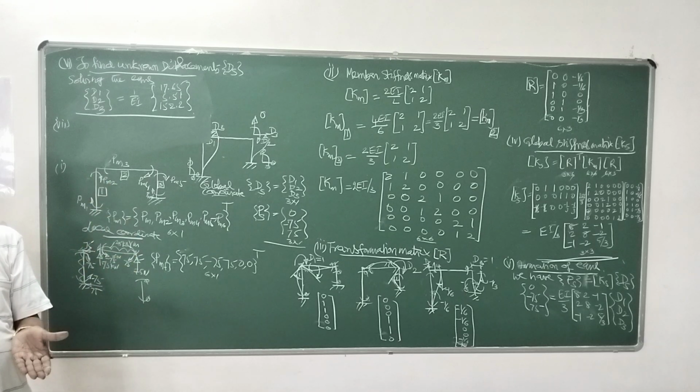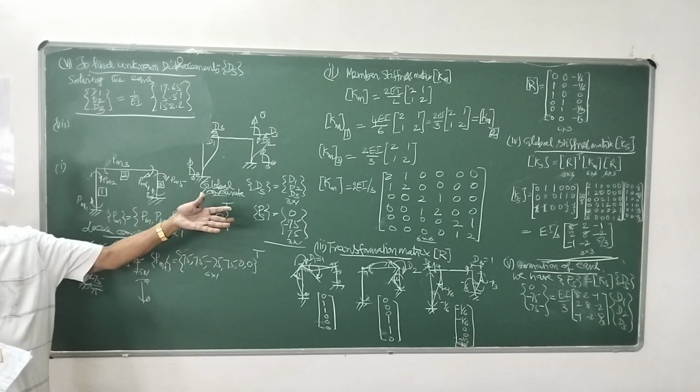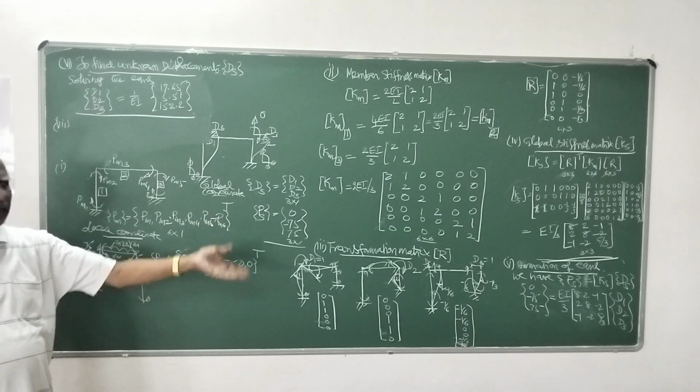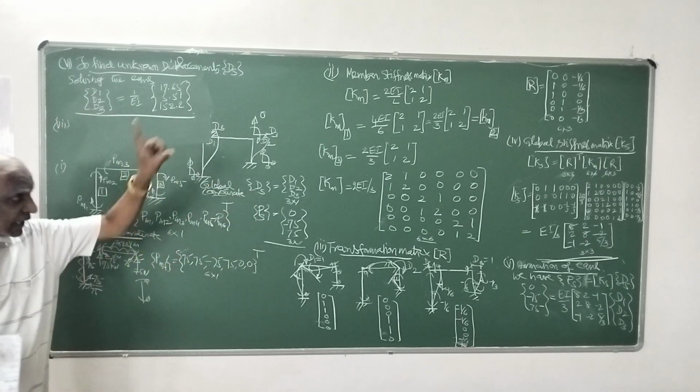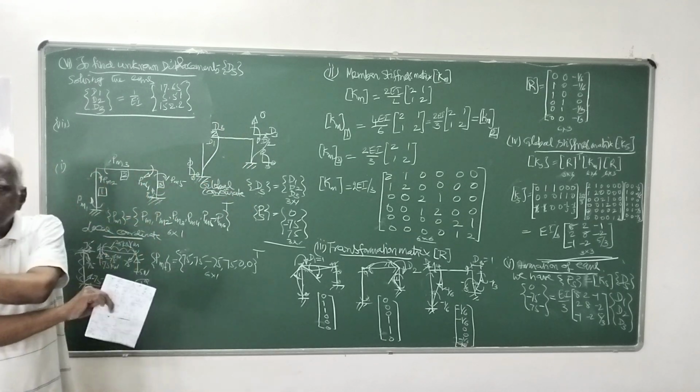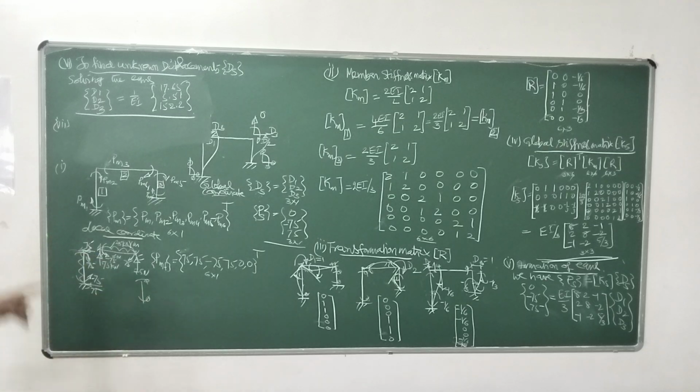So in the natural coordinate system, we determine Km, and for the corresponding rotation matrix, we determine it, and we arrive at the global displacement. Except for that change, the element property and element equation formation, no other change is there between the classical approach and the finite element approach. That's why in the syllabus they have told only analysis of plane frame structures, that too frame structures, one-dimensional structures, no two-dimensional problems. It's a very simple, straightforward syllabus.